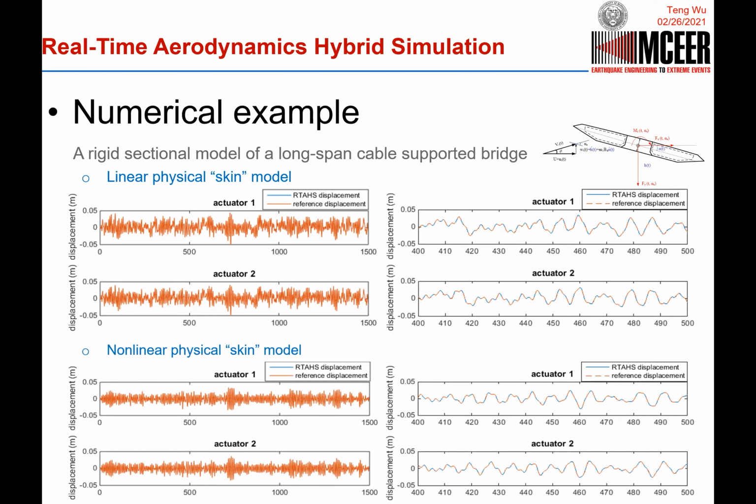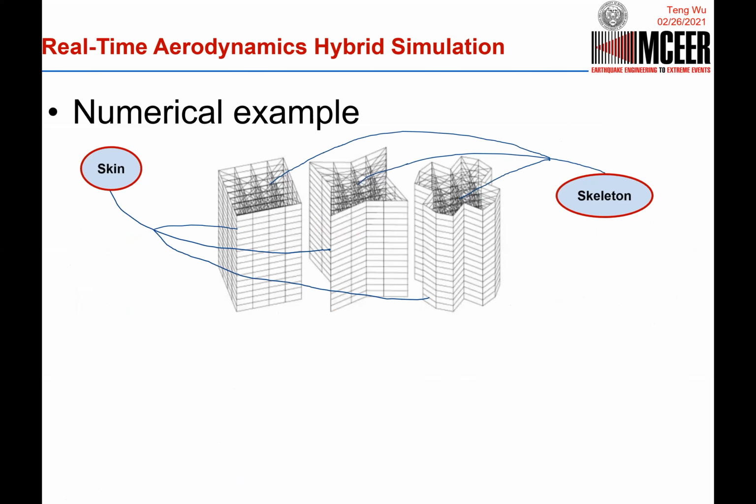So now we understand real-time aerodynamics hybrid simulation. The essential idea is, as long as we put the section in the wind tunnel, all the members, components, and even the energy dissipation devices enclosed by the section can be put in the computer numerical world.